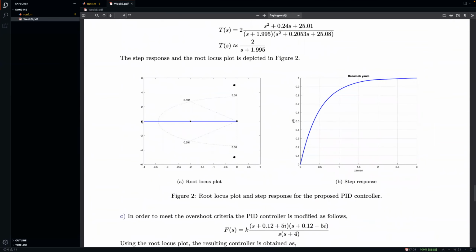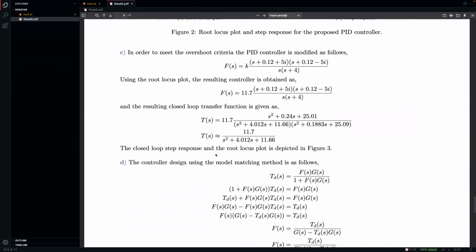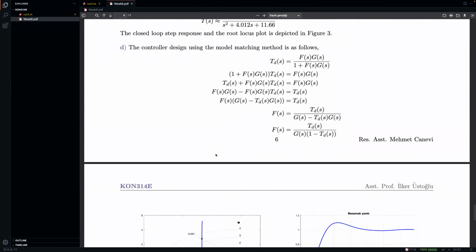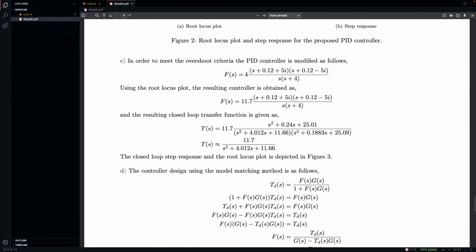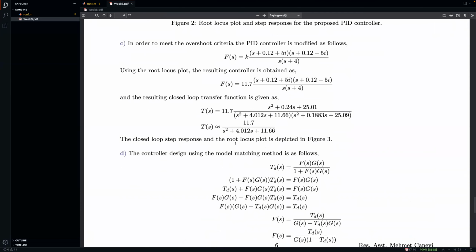When we add the pole at -4, due to the symmetry, it would go to j infinity and minus j infinity, and this would be the line that we are interested in. Then we can just use the intersection with theta, and this point would then correspond to a certain gain value, which we've then calculated and designed our controller. If this cancellation is done, we can see that it is kind of a second order transfer function, and that's exactly what we're looking for here.